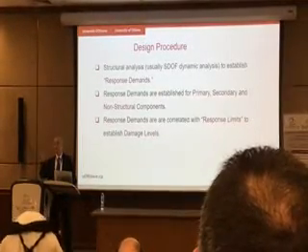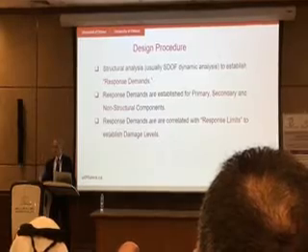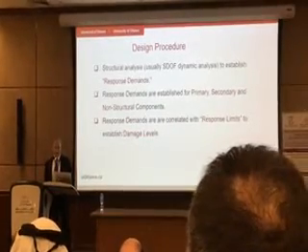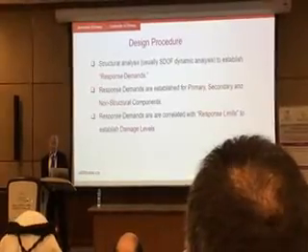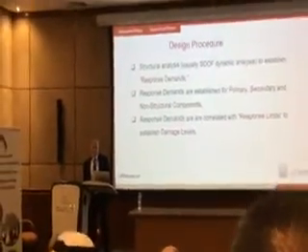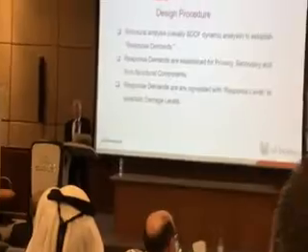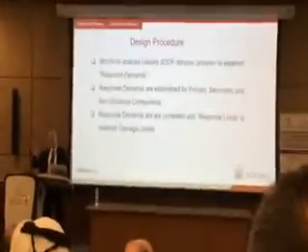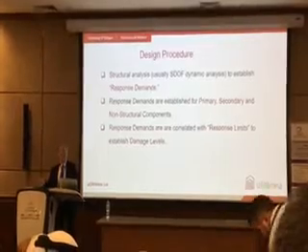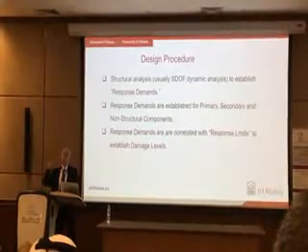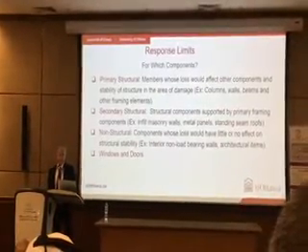So you have to design in detail for those two demands. And similarly for non-structural elements, I'll talk about window design and wall design. And then we correlate this demand with capacity. If capacity is higher than demand, then we're in business. Otherwise, we have to go back and increase capacity.